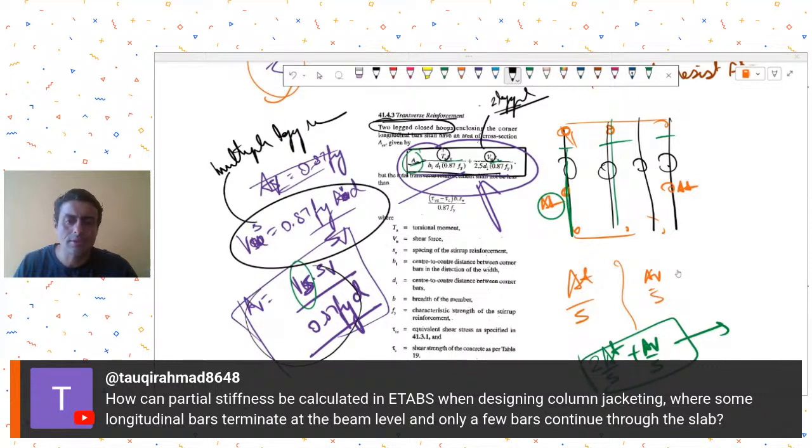more than reinforcements. Okay. Now, if it comes to, let's say, a beam column joint, and then you want to calculate the stiffness, then that's a different issue. Then it will depend on how many reinforcements at what location, and which reinforcement is going inside the beam, and accordingly, then you might have to come up with some technique to calculate the stiffness. But if it's only the stiffness of column, or let's say only the beam, the reinforcement bars will not affect your stiffness calculations as such. Okay, because the moment of inertia added by the bar will be negligible.